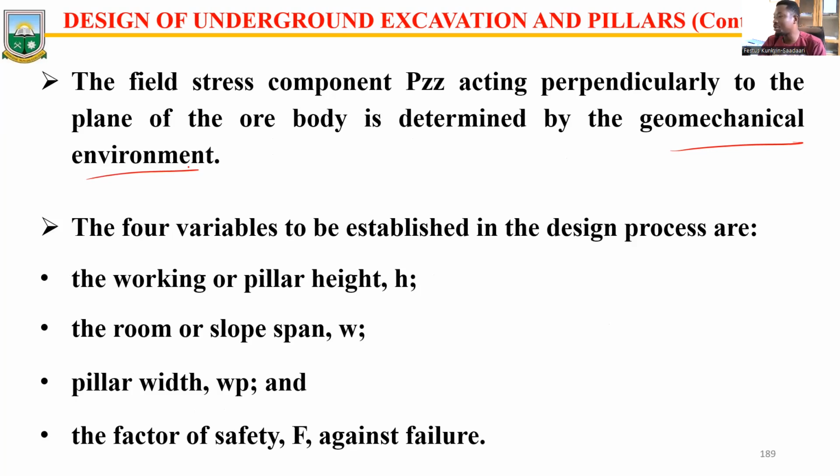So the 4 variables established are: the working or the pillar height, you should know that; the room or stope span, which is the width; then the width of the pillar. These are more or less a revision of the various parameters we have considered in the tributary area analysis. Then the factor of safety against failure.